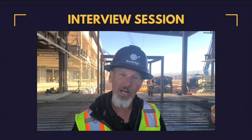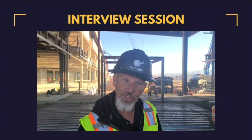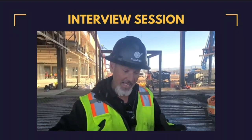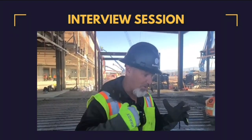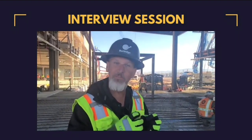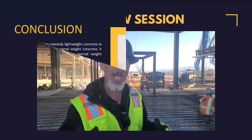The problem when you pump lightweight is this. A lot of people think when a pump can't pump concrete, the more pressure you put to it, the more it will pump. Well, what we found out is the more pressure you put with lightweight, it's compacting, it's putting more head pressure on that concrete, and it's absorbing the moisture into the material. It makes it worse. You have to finesse it through. You can't ram it through. You just got to ease it through.